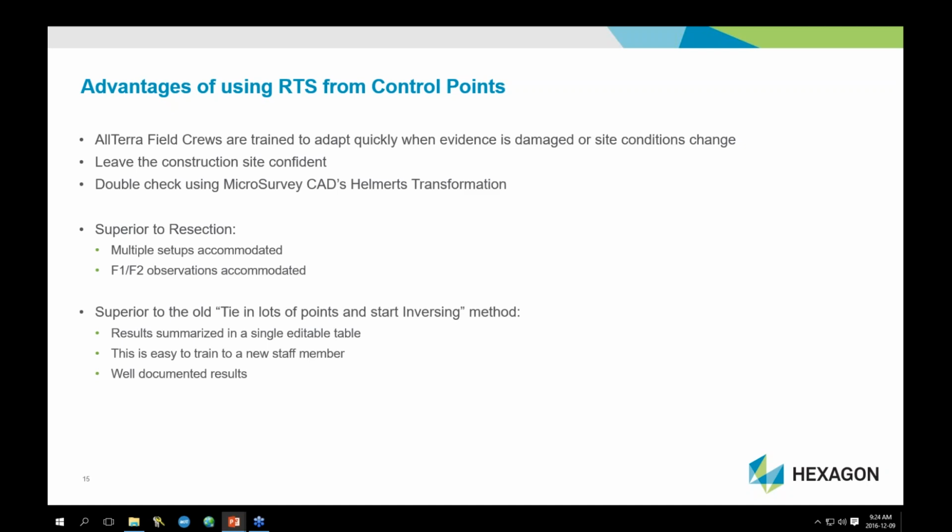I mentioned earlier the resection function is a good way to get started, but in my terms, it doesn't have legs. You can't run with it. You just have to use what you get out of the gate. Another thing with resection, we also use MicroSurvey StarNet here, and we adjust most of our legal surveys. Perhaps not something like a house layout, but if we were to send the crew out to do a preliminary survey for a subdivision, they would use the same localization function to get hooked into the site so they could search for the other iron posts they need to find with precision.